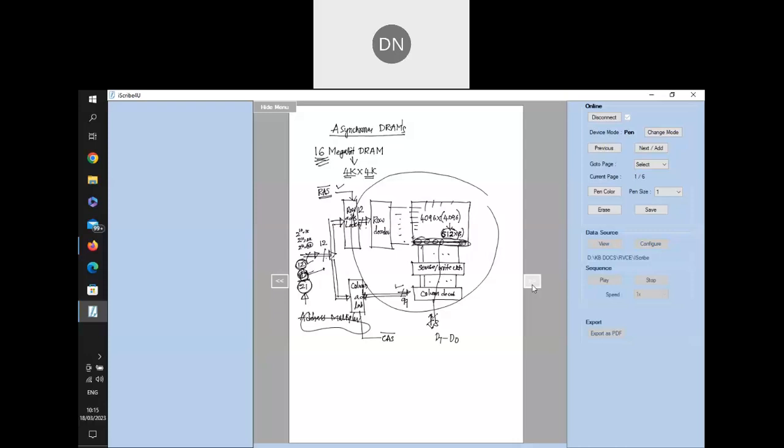This concept is used in almost all DRAMs. Why is this concept used? Because the number of address pins is large, so address multiplexing is used. Since you have to generate RAS and CAS signals, you also have to do refreshing. Within every 64 milliseconds I have to refresh.